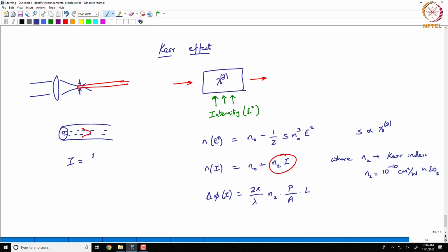And of course what matters, like we say in this case, is the intensity of the light, which is power over area. And let us say the power is only 1 milliwatt, okay. The area corresponds to what? How do you quantify the area? Is that the core area? As far as our optical fiber is concerned, we realize that you have light that is propagating both in the core and the cladding. So, what makes more sense is not the physical core radius, but the mode field radius.